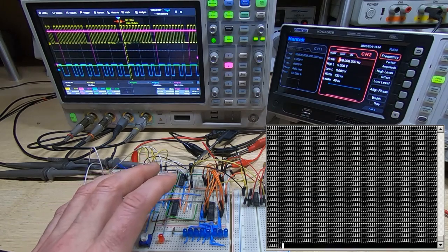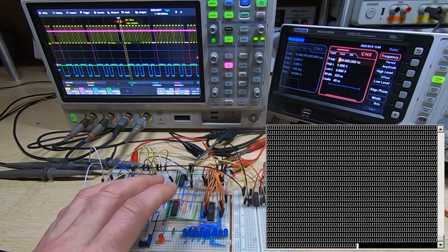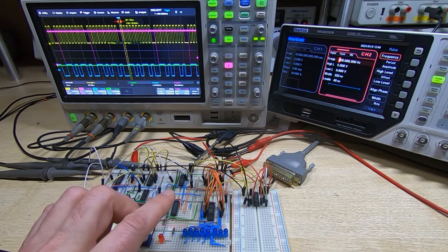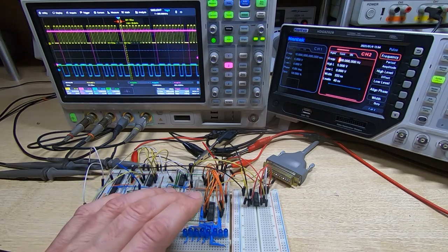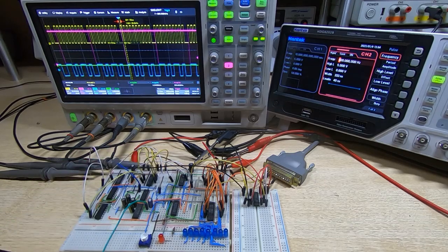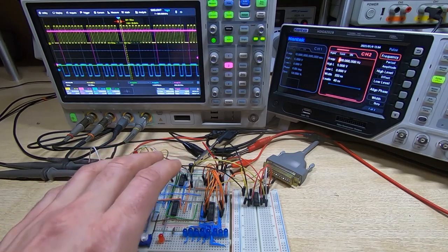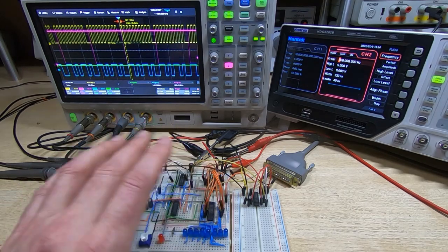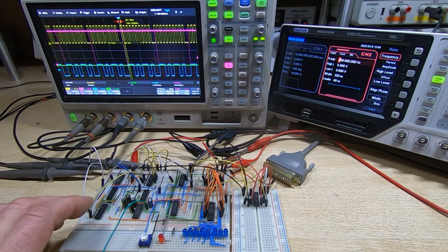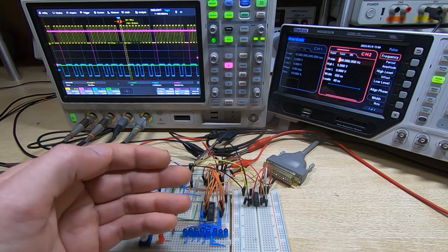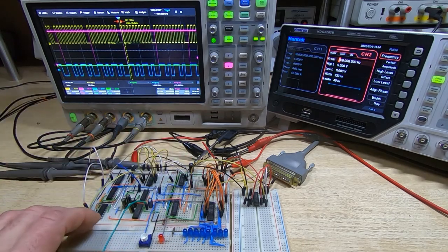If you want to include things such as CRC checksums, that sort of thing, remember the Z80 can do that in the same way it can generate parity directly from data fed into it. You can do that within the Z80 itself. So we're not necessarily completely throwing all that away. We can still implement that if we want to. It's just up to us to do that in either more hardware or in software.